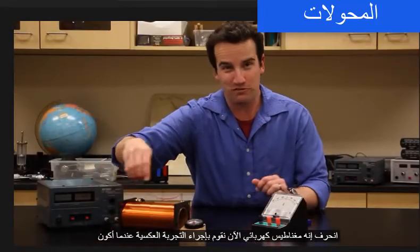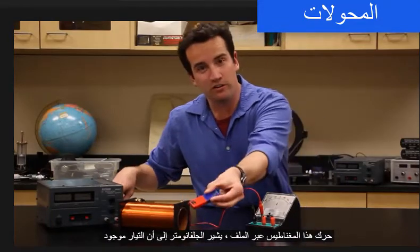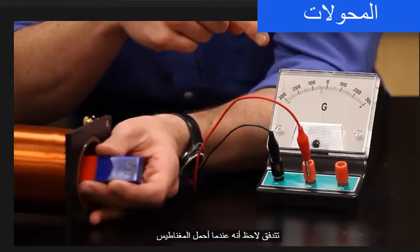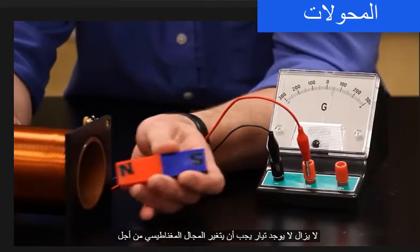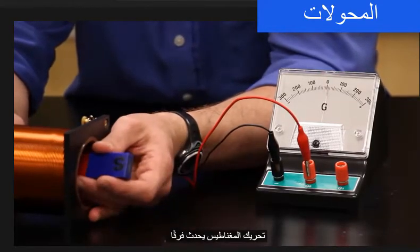Now we perform the reverse experiment. When I move this magnet through the coil, the galvanometer indicates that a current is flowing. Notice that when I hold the magnet still, no current is produced. The magnetic field must change in order to produce an electric field that motivates the charges. Note also the direction I move the magnet makes a difference.